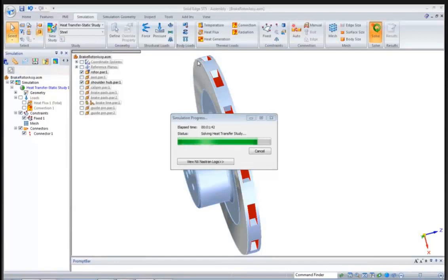and now I've got diffusion, so I've got the molecules here bumping into the air molecules here, or whatever fluid this is. Let's say it's water, whatever. Well, we'll just say it's air. So they're bumping into the air molecules, exciting them, and you've got that transfer of energy. So those are heating up the air molecules with diffusion. Well, also those air molecules are going to start to rise because they're getting warmer and they're getting less dense. So you've also got this bulk fluid motion.